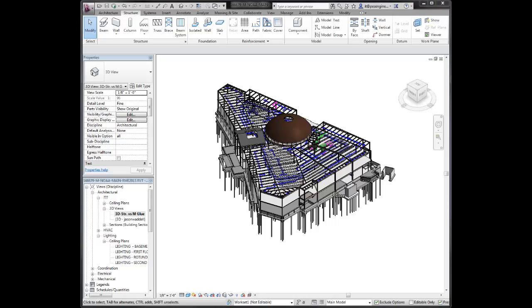Back in Revit, we will want to be in a 3D view, and of course, we are in the mechanical model. We have already linked the most current structural model that we downloaded from Glue. Similar to what we demonstrated earlier, it may be advantageous to have a preset view defined to match your subsets in BIM 360 and to have the visibility adjusted accordingly.